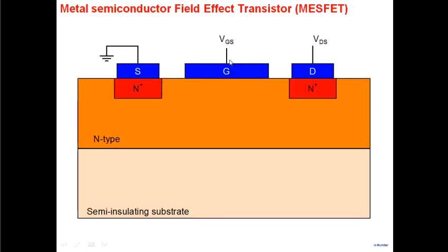Look at this one now. This is the basis for a very important transistor called MESFET, metal semiconductor field effect transistor. Can you see a transistor here? What do you need for a transistor? That the current between source and drain should be altered by a third terminal, which is the gate, right? You want transconductance. Will we get a transconductance? Will a voltage here alter the current flowing between source and drain? Yes or no? Everybody sees that?